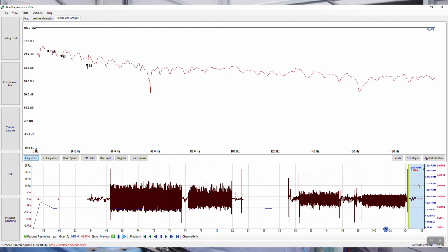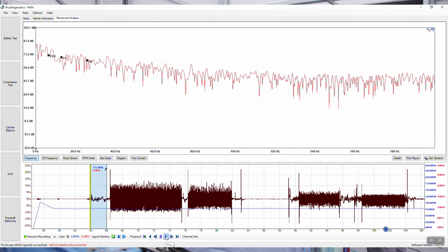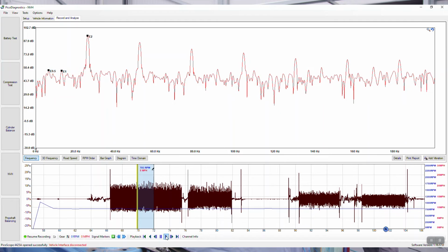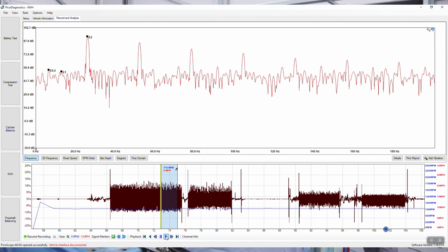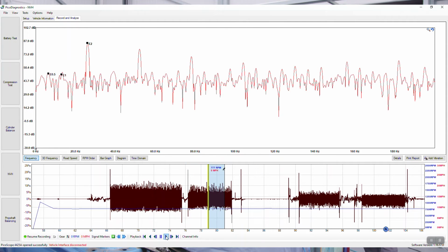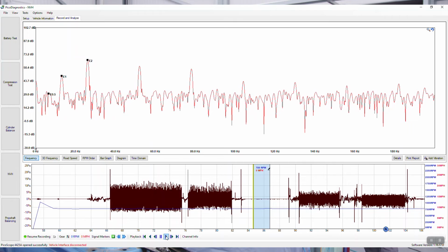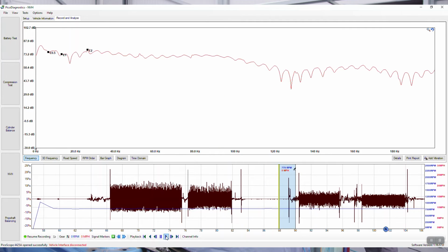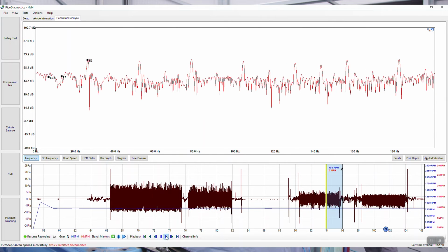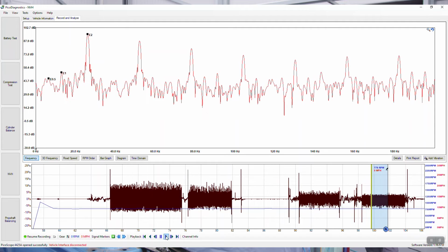Because we've actually connected the accelerometer as a microphone, we can now play back this audio. So if I press the play button now, we should be able to hear, there we are, there's our injector pulsations. Notice the amplitude as well by comparison. Next was on the engine lifting bracket, so that's general engine noise. Then we came off there and there was virtually nothing in the chassis. Of course there will be vibrations, but audio-wise virtually nothing. Next was the alternator, that was just purely holding it on the body of the alternator. And then finally, air conditioning pipe work.